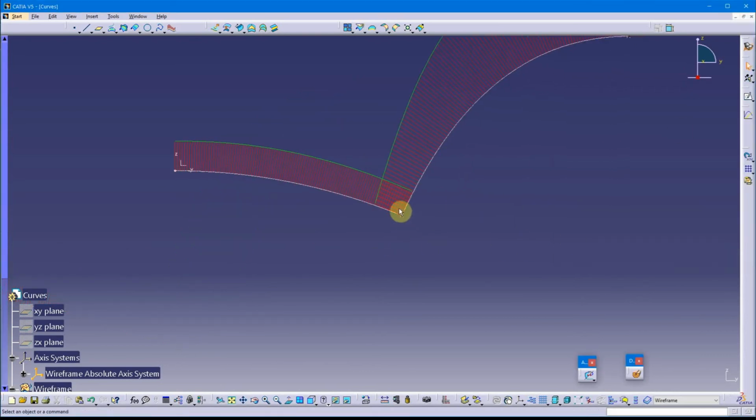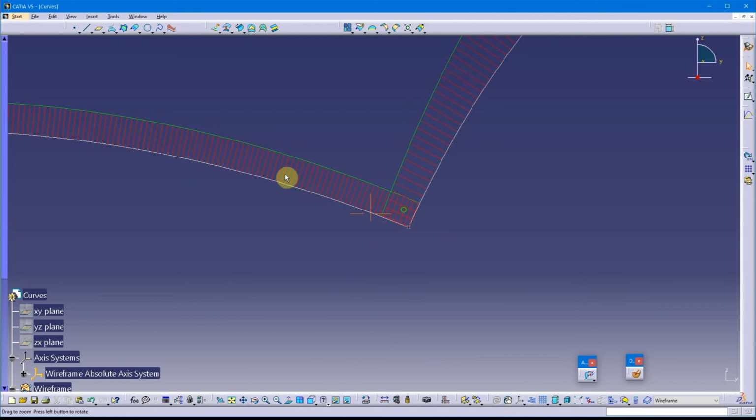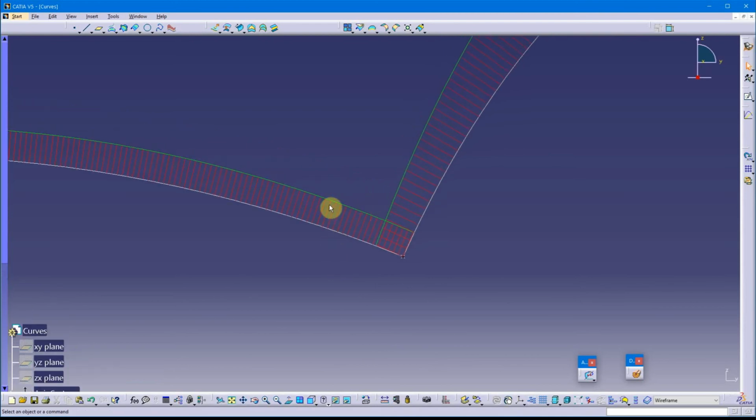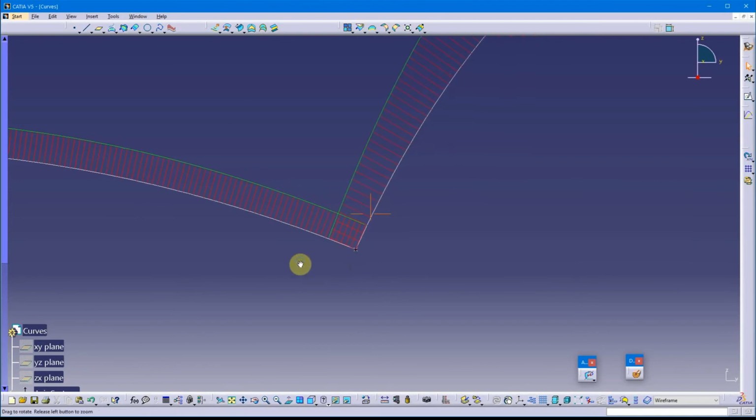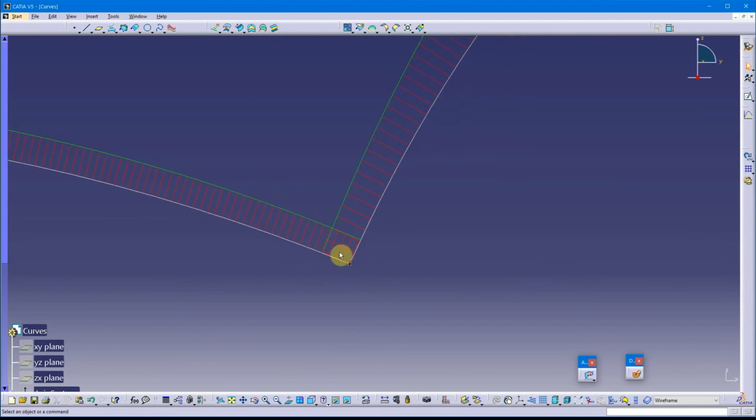But I still have G0 across here. And you can tell that because these quills on my porcupine analysis represent the slope and curvature of that point. And so notice their slopes are going in different directions, so they're not tangent to each other.